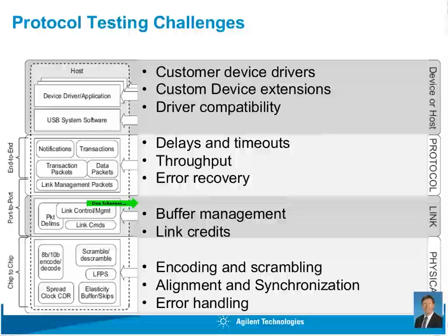You also need to be able to look at when things happen at the low level. What's going on in the operations for communication, if there's an encoding error, or if the LFPS signals are not happening in the right timing frame. Being able to capture all that and synchronize all that information together into one communication, and see the entire process for what's happening there.